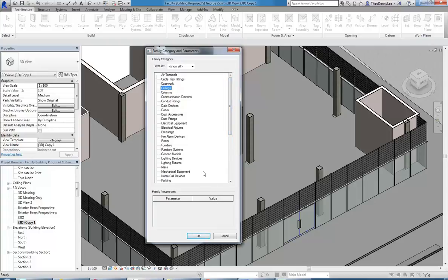And that's an important realisation, because if you need to use a modelling tool to create, for example, a wall that you can't create using a basic wall, in other words, the wall tool on the architecture tab, the only option is to use model in place.